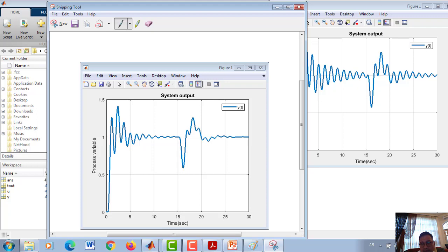The controllers of the modified Smith predictor are designed using the direct synthesis approach. The proposed method involves two tuning parameters whose suitable values are recommended after studying their effect on the closed loop performance and robustness. This is the main advantage of the proposed work over other recently published manuscripts, where the authors do not provide a suitable range of the tuning parameters.